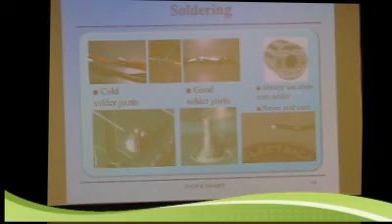You always use rosin core solder. Never use acid core. Acid core is used in some cases for galvanized soldering, that kind of thing. Solder is essentially a way to connect two wires, mainly electrically, but it can be a pretty decent mechanical connection as well. Good soldering gives you lots of good use over the years. Poor soldering will give you headaches over the life of whatever it is you do.